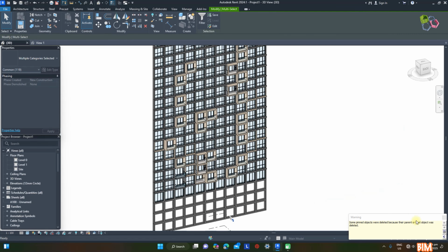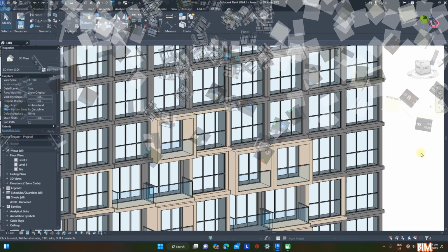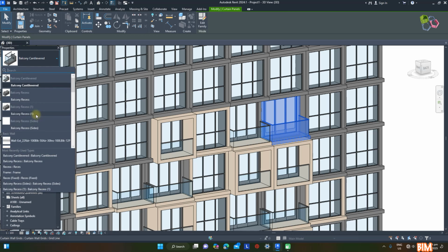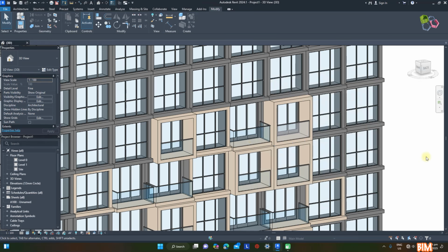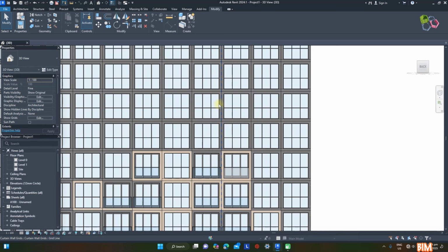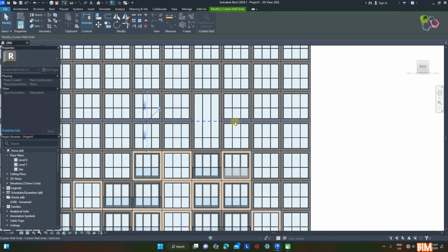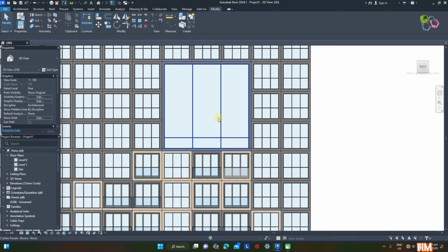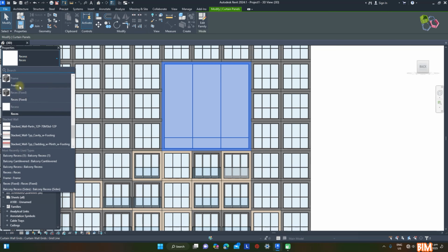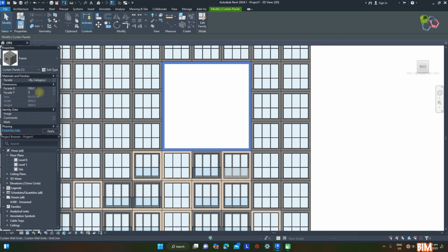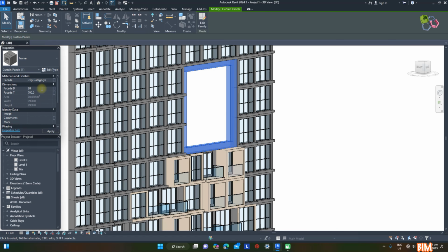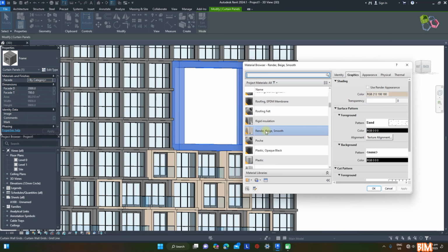Then, remove the sample curtain wall from the project. Large frame components are added by removing curtain wall grids and replacing panels with oversized frames. Apply facade T, thickness, 500 mm relative to its size, and facade D, depth, to 2000 mm. Materials are applied to those as well.